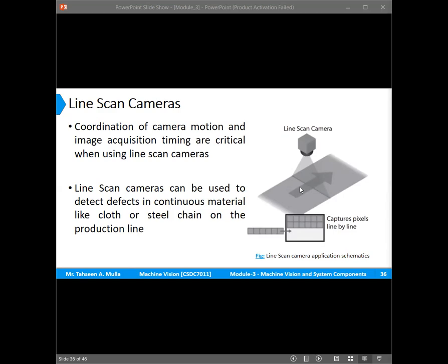If you remember, I have given you an example in a mechanical industry where we cannot see the edges, or if there's a crack in a metal sheet and it cannot be identified by the human eye, line scan cameras can really help us in this scenario to identify those cracks, or if some of the edges are folded, for a metal sheet. This entire structure to identify objects internally and on the edges can be really helped by using line scan cameras.